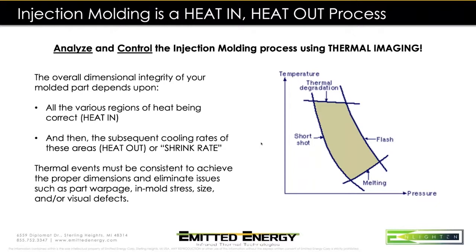And ultimately, some of those decisions come into play of the need of how bad you have to ship the part, unfortunately. But what we talk about here is, let's take a knit or a sink. We've done a DOE, we know exactly what the perfect part is, and it's supposed to be at 175 degrees on one side of the knit line, and 174.5 on the other side. And if it's not, and something's different that's happened in the flow, or the material you're getting from your material supplier has changed, we'll pick it up right away.